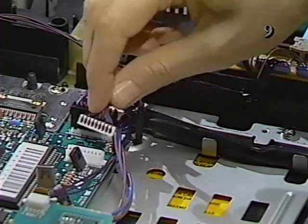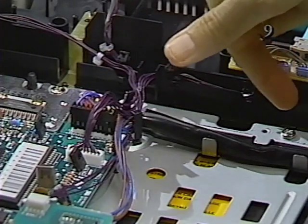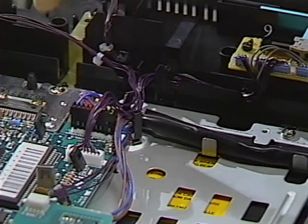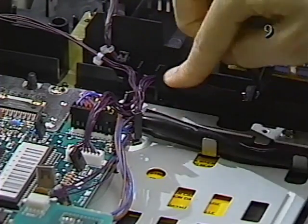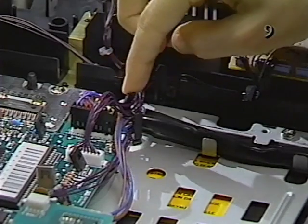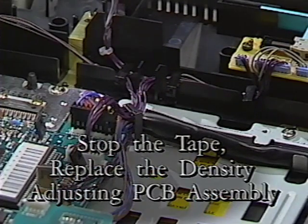Reconnect connector J213 to the DC controller PCB. And finally, replace all connector cables in the black cable clamps and close the clamps. Stop the tape and replace the density adjusting PCB assembly.